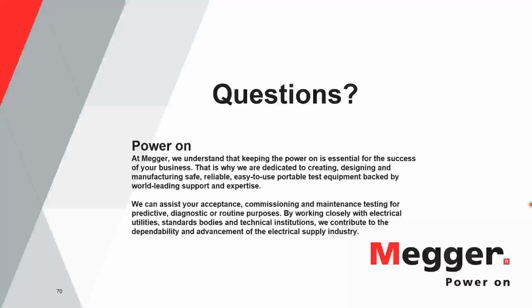Maybe I can add a little bit on that one. If you look at your short circuit impedance kind of test, and you look at the short circuit response on your sweep frequency, you will see that the very low frequencies have to match the three windings. Okay, and you will see that the response is very close to 0 decibels. That is a pattern to follow. And then when you go beyond, maybe say, around 100 kilohertz, you will see that now the windings are reflected and the response is very similar to your open circuit. So those are the little things that you have to look at on your short circuit response.